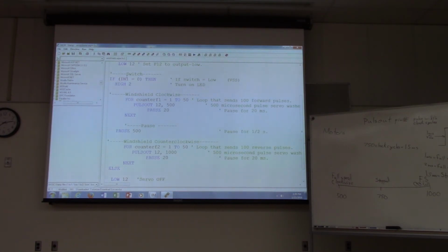So the voltage on pin 1 can do what we call floating. The voltage can go up or can go down depending on, you know, the static electricity in the air, or whether somebody bumped against it, or things like that. So it is important to have the wire there. I got lucky when I was running it earlier in the class, and it happened to be in the state where the motor was running, but it is not necessarily going to be that way. So it is important to put the switch in. Okay? Does that make sense?